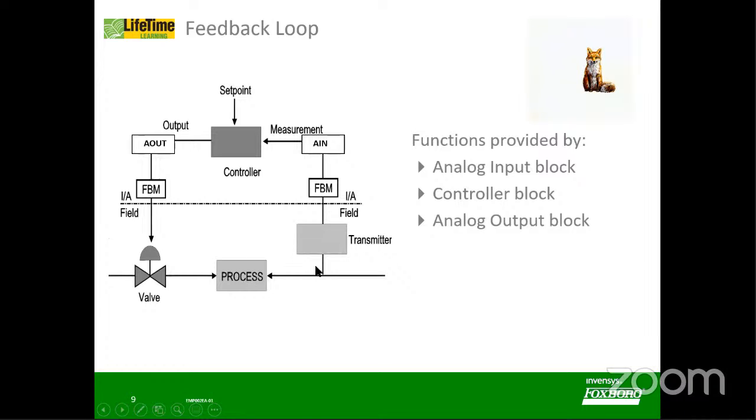Fine. Now, before this process, you have some input transmitters. Let us say in this process you want to control level, temperature or flow, whatever. To do that, you have a transmitter. Those transmitters may be simple analog transmitters, or HART transmitters, or maybe Profibus, Fieldbus hardware, whatever.